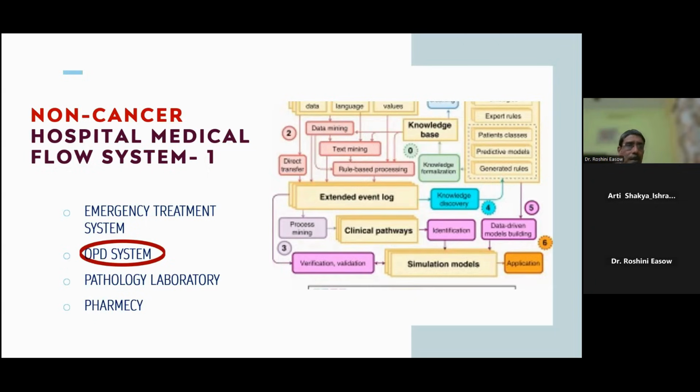Because the external client, the patient coming in, we don't know what disease they are carrying. Maybe there are some viral infected patients. What will happen? They will donate their infection to the air. Now, if you allow the main hospital air and OPD system air to mix together, there is a chance of spreading infections, because we don't know who the patients are. So this is a very critical area I am explaining. Then he accepted it in a one-to-one discussion. I told him to bring the OPD air distribution system separately from the main hospital.